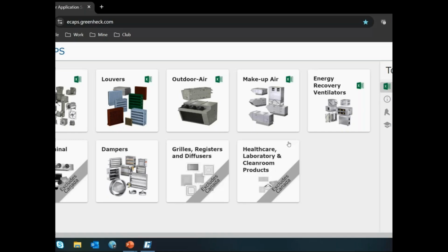Well, here's reality. When it comes to getting the right amount of air movement with a little bit of system effects in play, if I had made a conservative or a really good selection up front, that fan might have the capability to push through it. I might have the room to turn up. Now that's minor system effect. You start going into major, well, we've got bigger things to worry about.